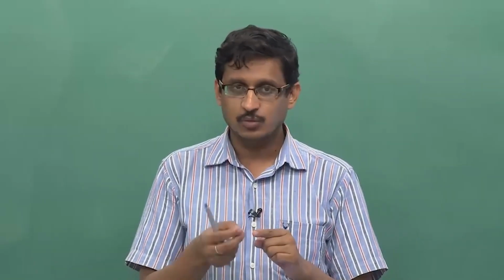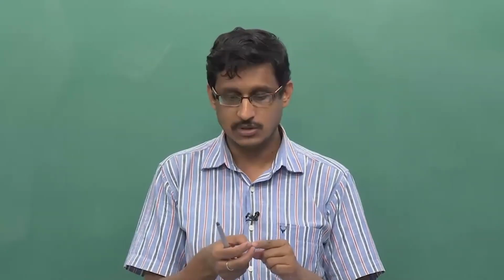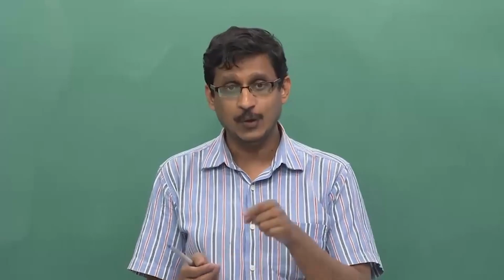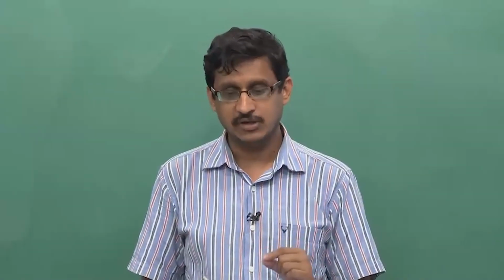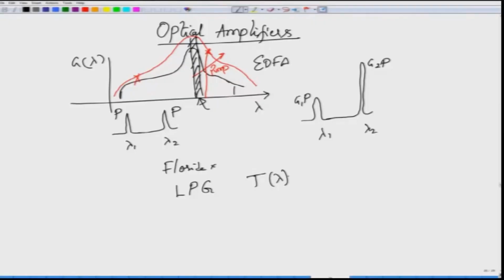Okay, the reason we used a long period grating, or at least I mentioned that we used long period gratings, was gain equalization for an erbium doped fiber. It is possible to fabricate a long period grating whose transmission spectrum, say T of lambda, is such that G of lambda coming from the erbium doped fiber and T of lambda coming from the long period grating together can be made uniform,